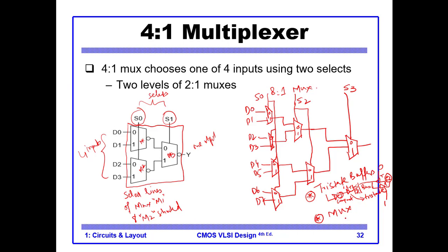But the mux is an interesting element. You can also use the mux for this kind of functionality. If you want to put something on the bus, you can use a mux. And because a mux can also give you, if you want to connect, for example, 10 elements, if you have two components, C1 and C2, and this is your connection to the bus, you can put C1 here, you can put C2 here.